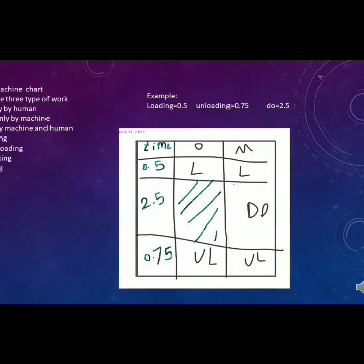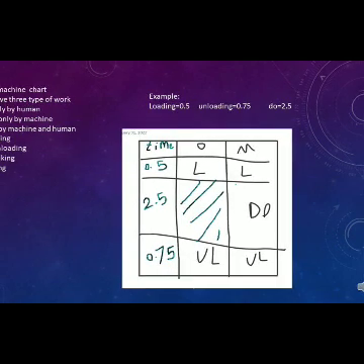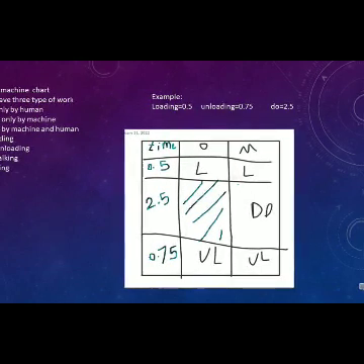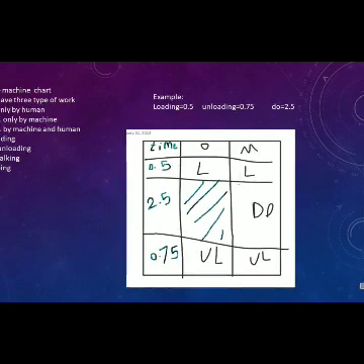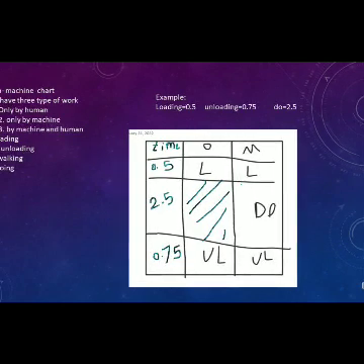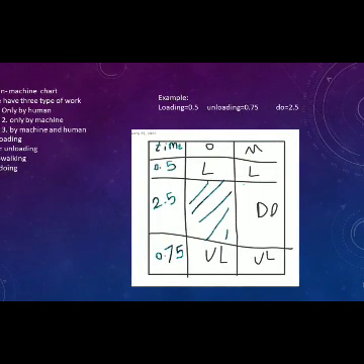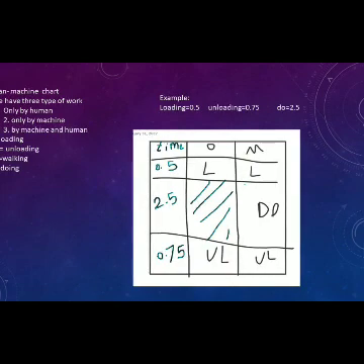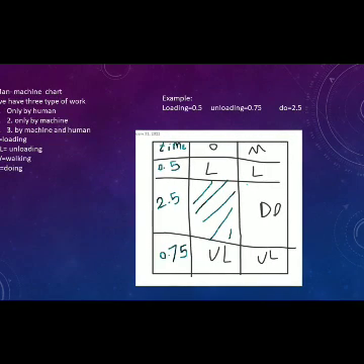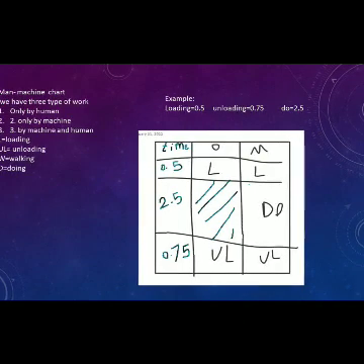And for explaining, the capital W means that if there is distance between machines, then the operator has to walk between machines, so it takes time. The W means the time that the operator spends to move between machines. And the doing is the time that the machine needs to work on the part.